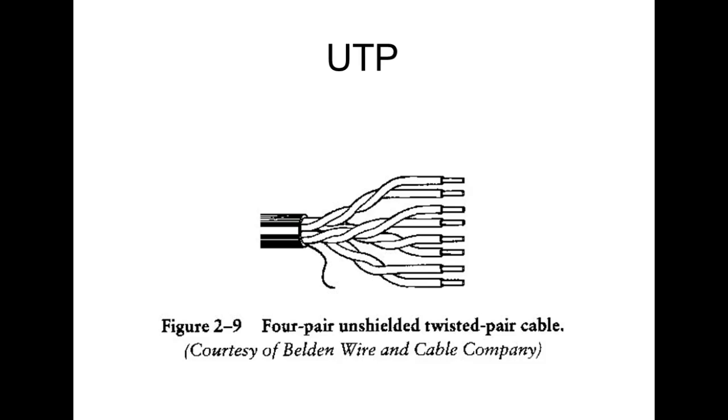We have two categories. We have what we call unshielded twisted pair, UTP cable, which is what you're looking at there. If this was shielded cable, it would have a metal foil wrapped around it, and that would be a true shield. Remember, with true shields, you only ground on one side. Y'all understand why?